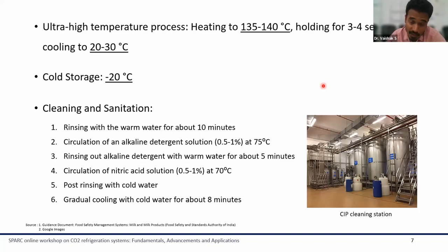The Tetra packs do not require any refrigeration until they are opened. The heating requirement for this kind of process is approximately 135 to 140 degrees Celsius, and it can also be considered a pasteurization or sterilization process. At this temperature, the process is carried out only for 3 to 4 seconds, and the product is immediately cooled down to normal atmospheric temperature, approximately 30 degrees centigrade. So that is another heating requirement at this dairy plant.